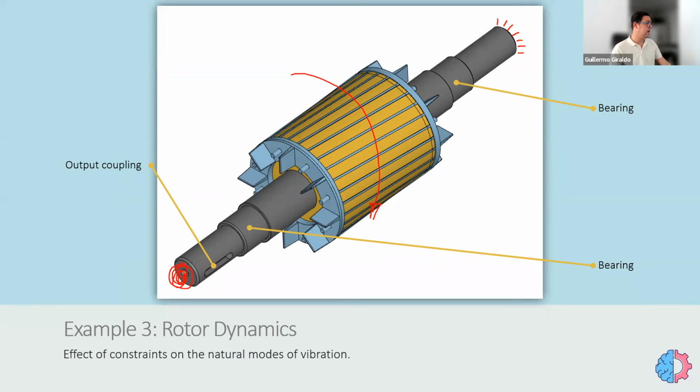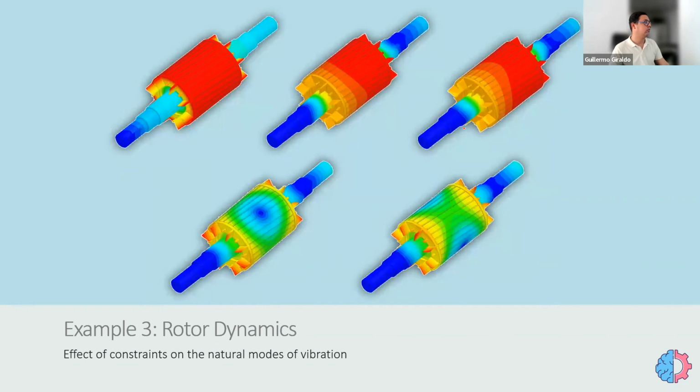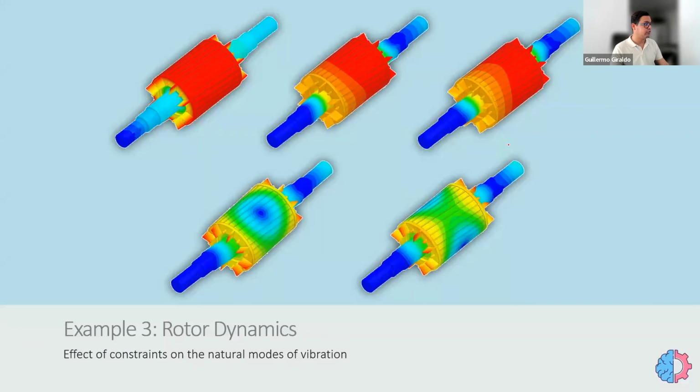So if you fix at the ends, the length is longer, right? And then you have a longer shaft, or say a longer beam, than if you fix in the correct positions. And then it will be more flexible, because you will have lower natural frequencies, and you are inducing errors in your model. So that's a very important thing. Just try to be as realistic as possible. And when you try to do simplifications, think very thoroughly about what errors you are inducing in the model.